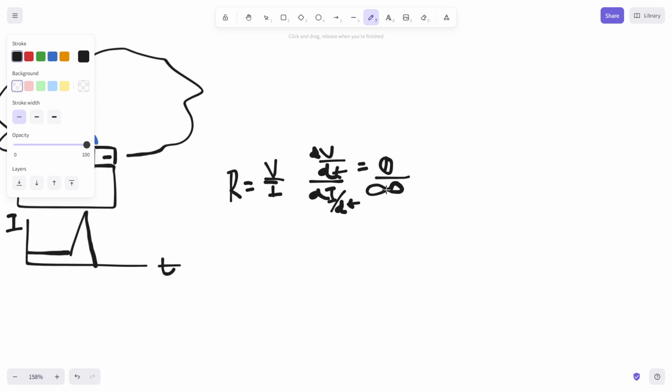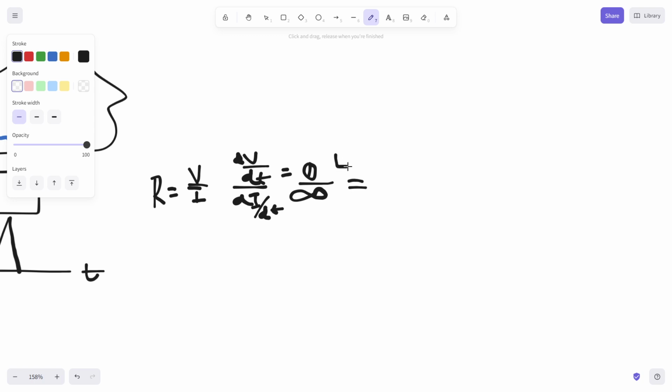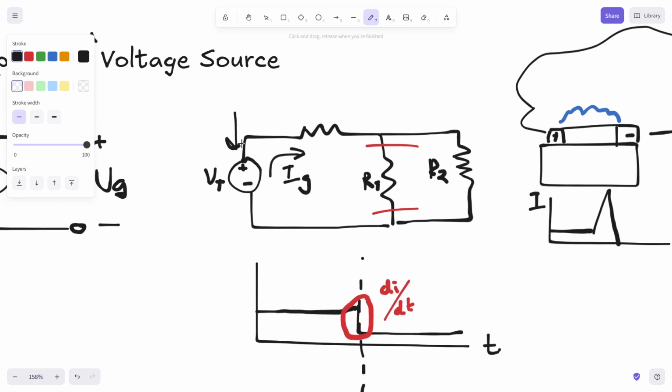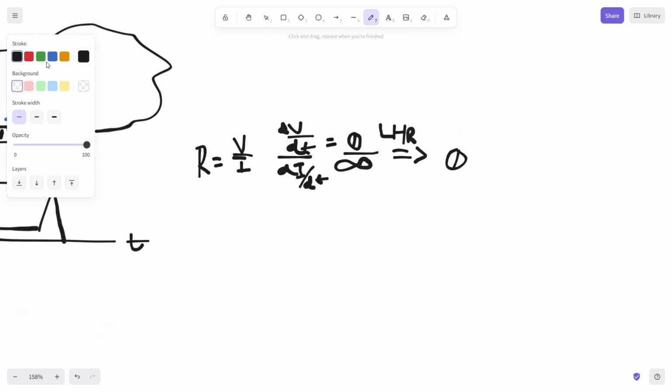And you think, okay, this is a very peculiar fraction. Your Calculus 1 students might say, oh, is this 0 or is this infinity? Well, if we just look at L'Hopital's rule, this just very quickly produces 0. So the resistance across this particular device, looking into its terminals, is going to look like 0 impedance, which is a concept that's going to be relatively important, especially when we get to equivalent circuits in the next episode.